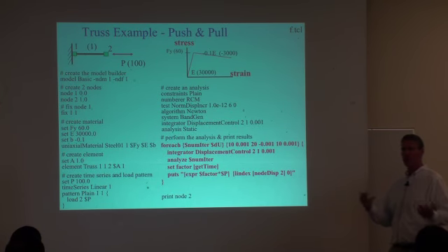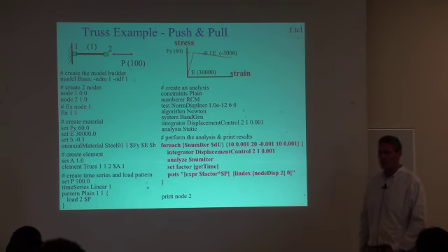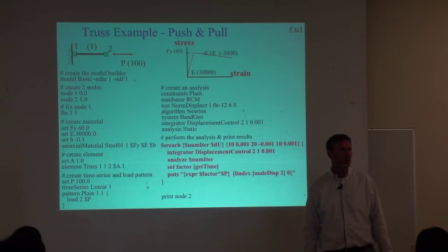And then again, we want to get what the load factor is coming out of the model, and we're going to put that out to the screen. So what this displacement control does is figure out the load factor at every step to give you the displacement increment that we're looking for. We'll talk more about that this afternoon.